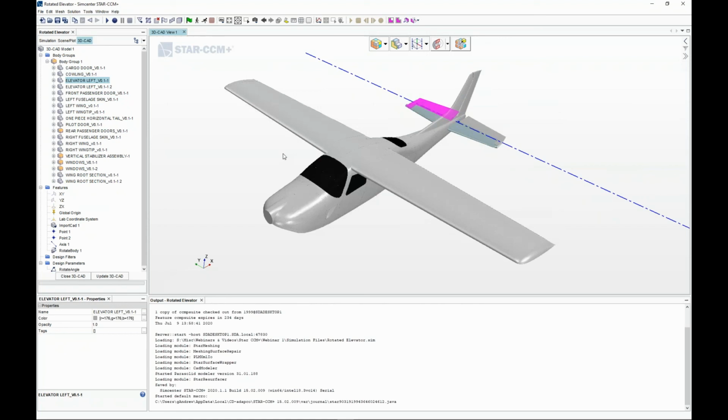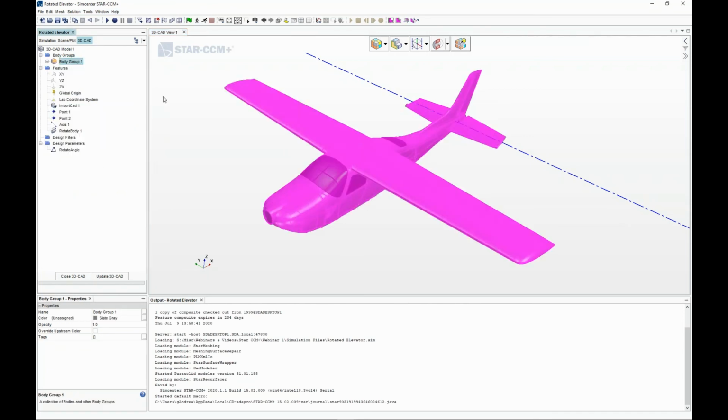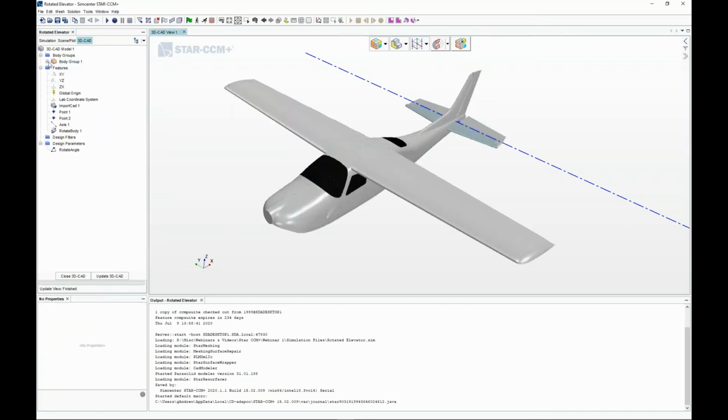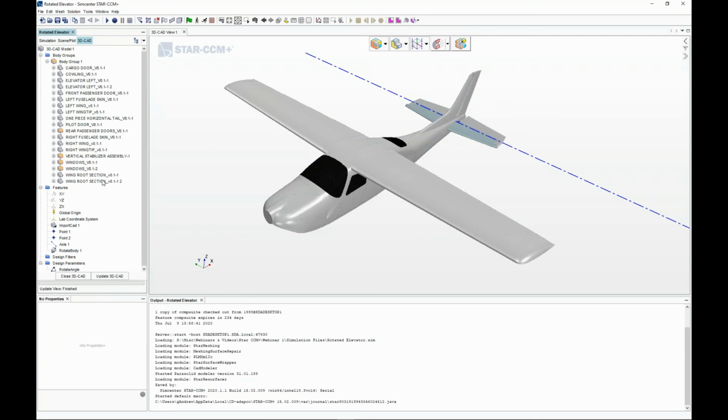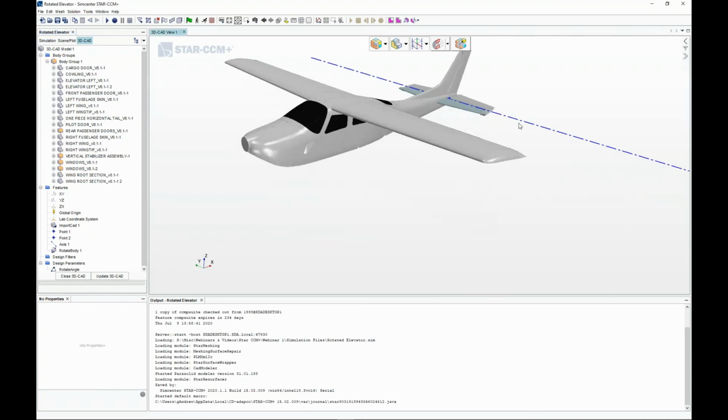You can also do that on the inside if you're worried about internal flow, where you expand a balloon on the inside until it touches all the internal surfaces, and that way you don't have to do all this geometry processing where you have to unite everything. That's an operation that's not in the 3D CAD modeler though. After you've exported this into a geometry part, you can then create a surface wrapper operation.